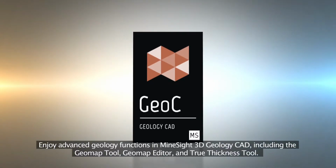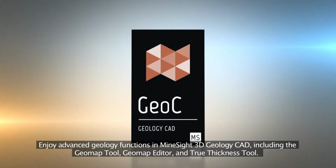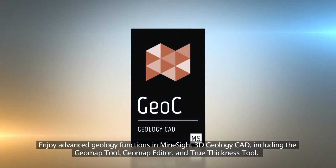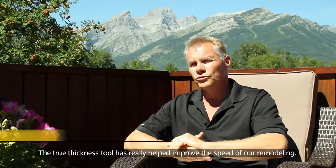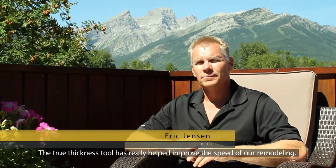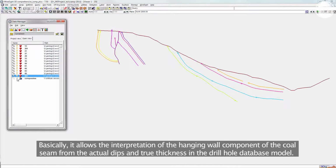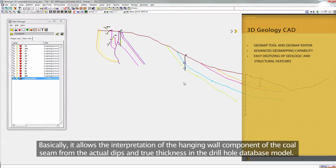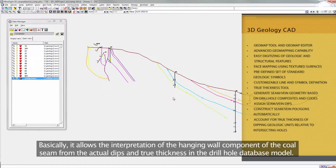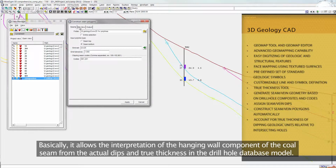Enjoy advanced geology functions in MineSight 3D Geology CAD, including the GeoMap tool, GeoMap Editor, and True Thickness tool. The True Thickness tool has really helped improve the speed of our remodeling. Basically, it allows the interpretation of the hanging wall component of the coal seam from the actual dips and true thickness in the drill hole database model.